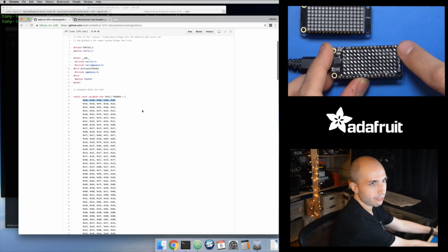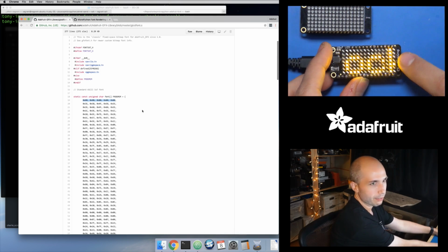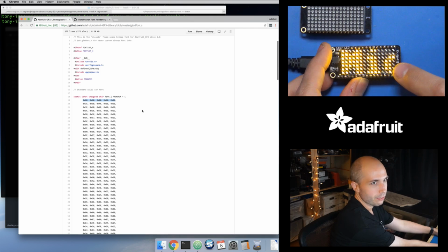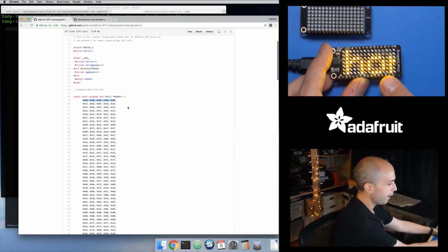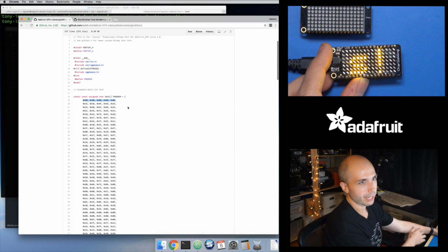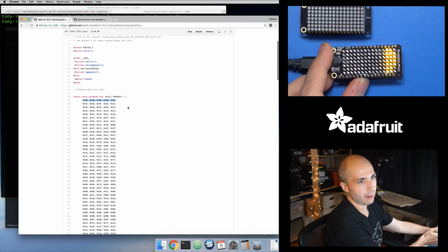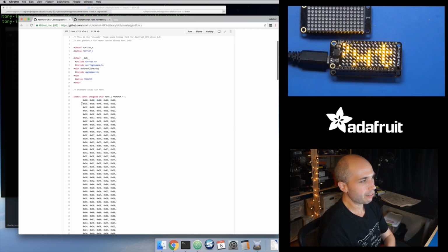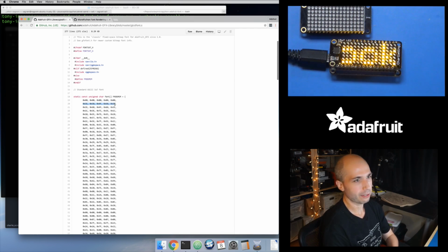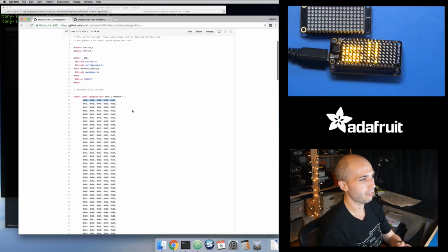If you look at the display, each column going down is 7 pixels on this display, but on the other one it's 8 pixels. So each of these columns is a byte inside of here, and 5 of those columns together make up a single character. As this thing scrolls across, like the PYTHON, each of those is a single character, so they are 5 bytes wide. And that's what each of the rows in this file defines. Character position 0 is the null character, which has no representation. But this is laid out by the ASCII characters.